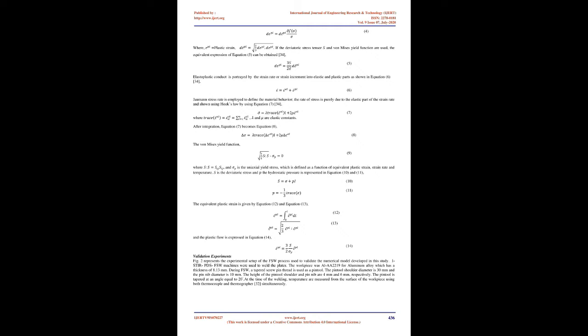Ongoing work done by Shi et al. 26 built a 3D model which is able to capture heat generation, temperature field, and material flow in the reverse dual rotation friction stir welding process. The reverse rotation of the shoulder and the tool pin is the dominant contributor to the heat generation rate. The temperature profile from the model and the experimental results match as well.